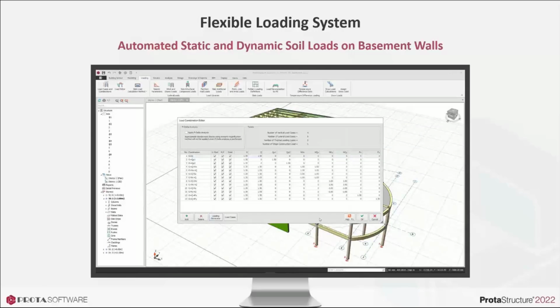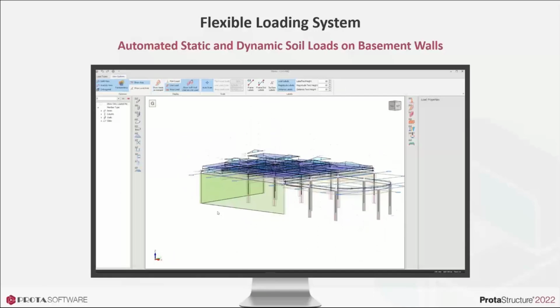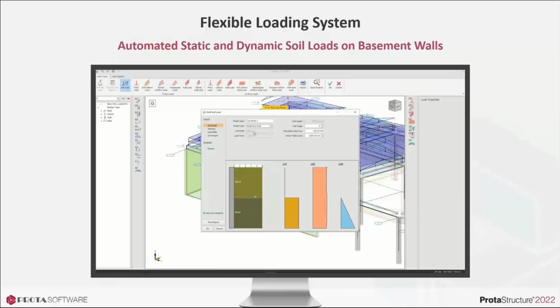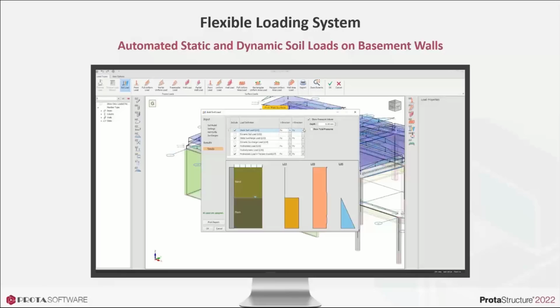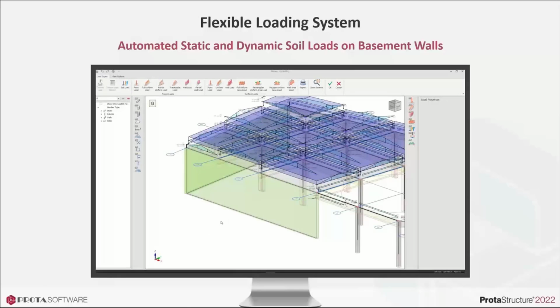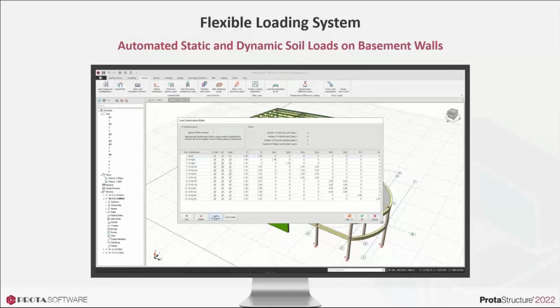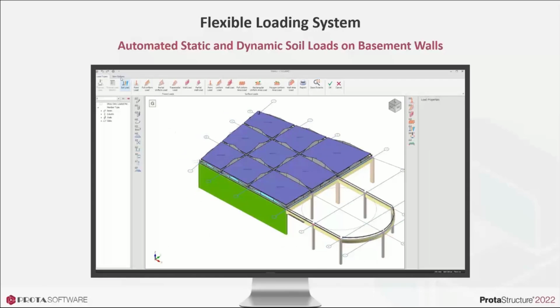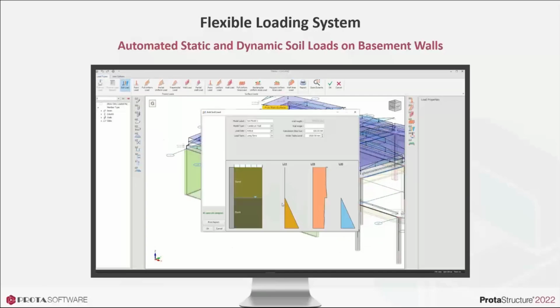So another essential type of loading is the static and dynamic loads of soils on the basement walls or parts of your building that acts as a soil retaining structure. So ProtaStructure will allow you to specify your soil profile, water table, and surcharge loads. Then static and dynamic loads will be automatically calculated and assigned to shear walls and basement walls. Of course, you can do further editing on the calculated soil loads and even create detailed reports